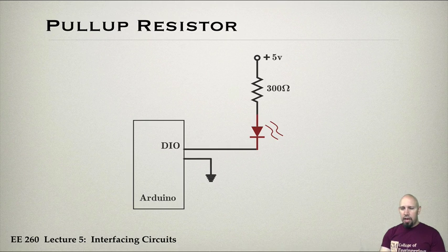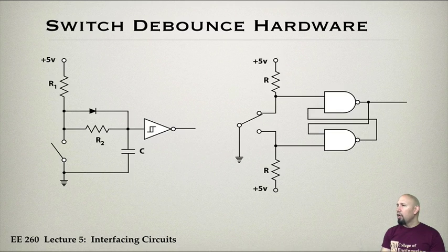And we're going to see some examples of circuits that require capacitors, like this one. This one requires a capacitor in here. So basically the R and the C provide a kind of low-pass filter here. And we're going to talk about now the switch debouncing. So we've talked a little bit about the fact that when you switch a switch from one place to another, it may bounce. It may bounce several times before it finally settles.